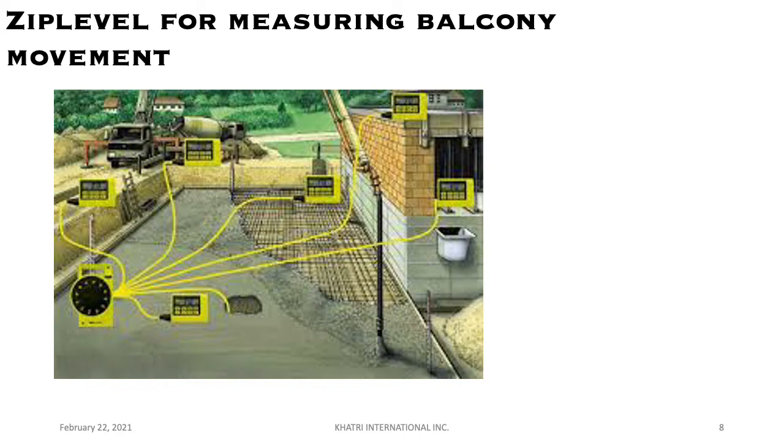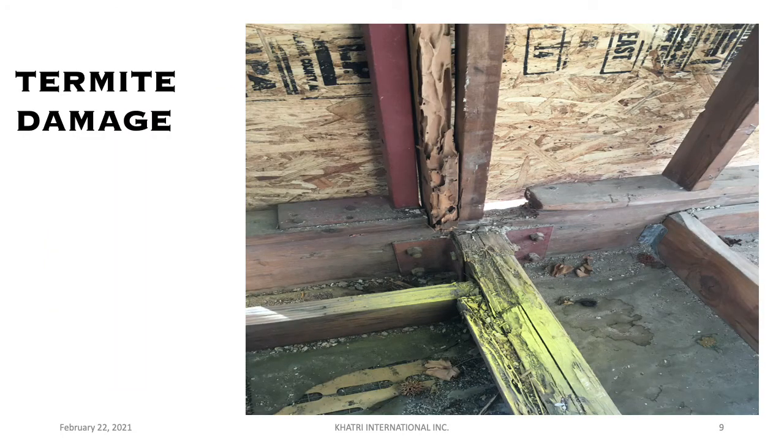And what we're doing is we are measuring elevations on that balcony to see if it is tilting, is it sinking, is it deflecting, and I have a short video clip which will show how we do that and what that means exactly. And we will do some destructive testing if necessary, depending on what the results are of the zip level survey.